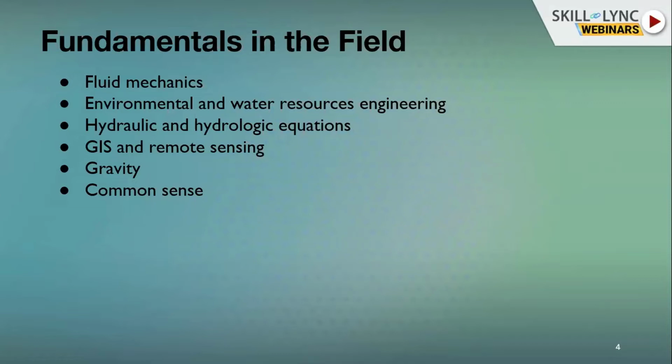Then they should also have good knowledge of their catchment, because they should really understand when a drop of water falls on the ground, how will it flow? People should know their catchment and what will happen when a drop of rain falls on the ground. Then these flow hydrographs are applied to our code area or our area of interest, and that is where our hydraulic model starts. These are the basic fundamentals in flood modeling that people should be aware of.